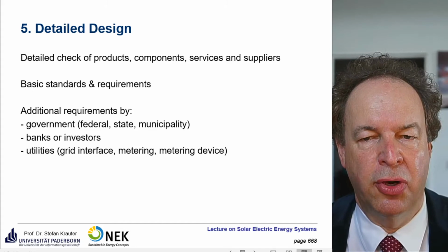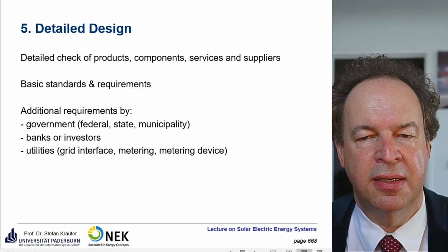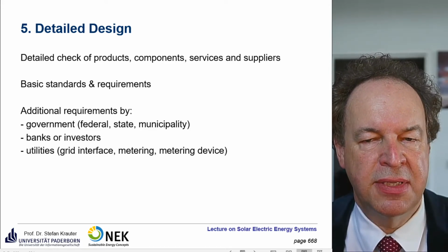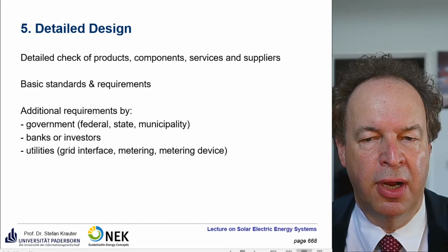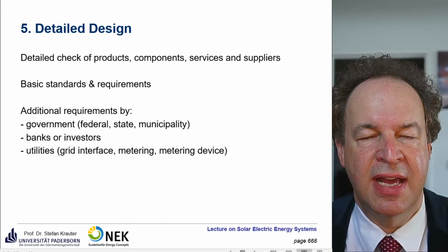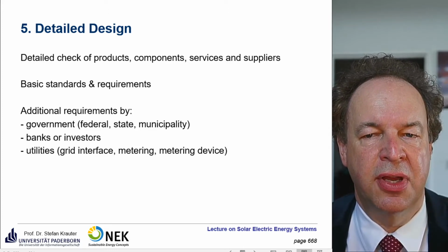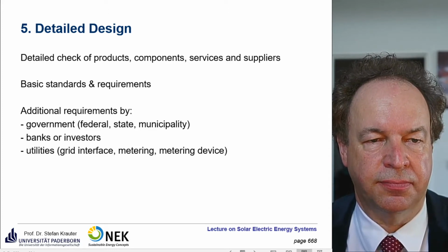So you say, for example, the module has to be certified for IEC 61215, or additional requirements, for example, PID, or if you have a farm nearby to be ammonia resistant, or if you are at the seashore, you have to make sure the module withstands salt mist and so on. So you have to choose an adequate norm for that and say, okay, this has to be a part of the contracts with the supplier.